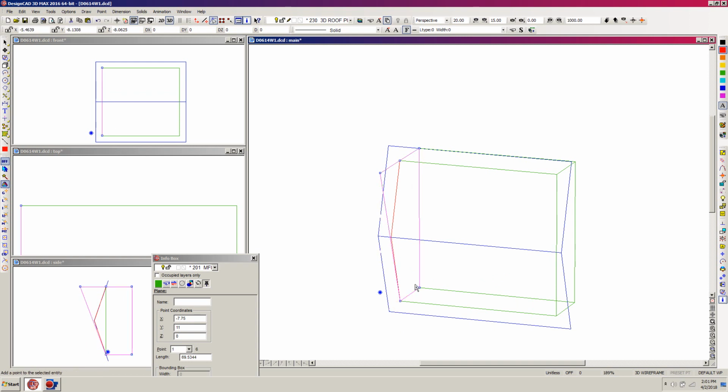Now this is getting kind of weird looking, but I'm just going to right click at this remaining top point here, and then right click to snap it to where those two red lines intersect. And you can see that I just created a wall and gable at the same time. So this is just basically one wall.